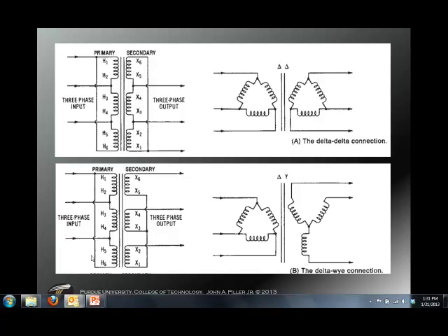So the primary is a delta, the secondary is a Y. This is the kind that you would see, primary being the utility side, because remember, they don't need to bring in a neutral to us. Secondary being the customer side, with a Y, because we want to be able to have this point right here, this neutral. So here, the primary, we already discussed how delta sets up.